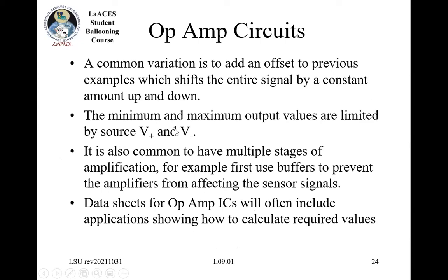One important caveat to note is that your output value is limited to be between the values supplied by the source. So the largest it can be is the value you give to V plus, and the smallest value it can be is whatever it's at V minus.